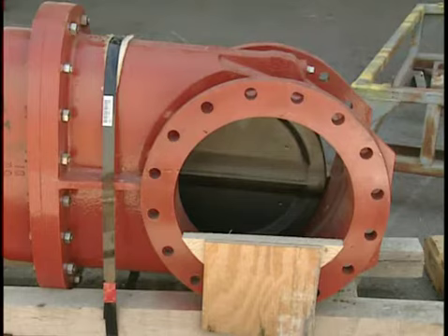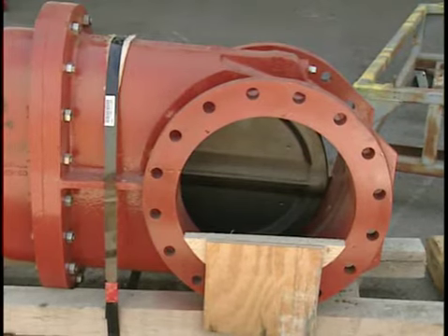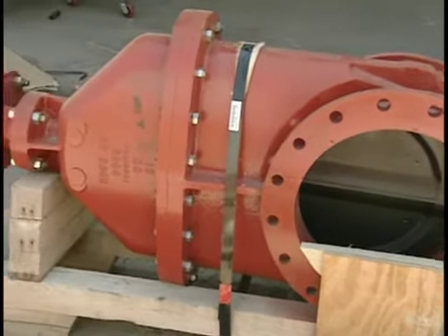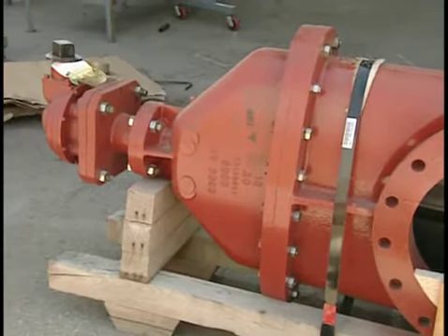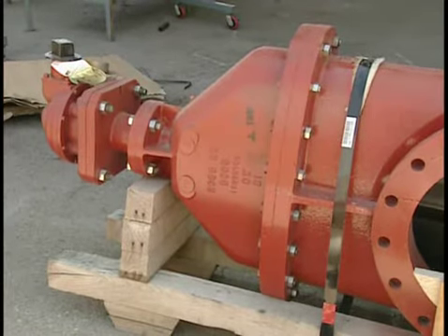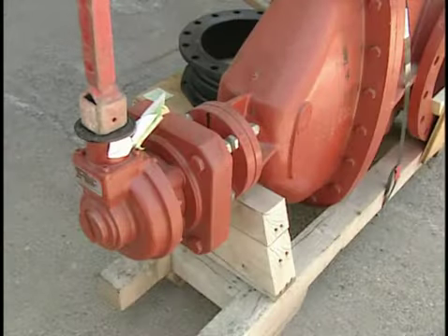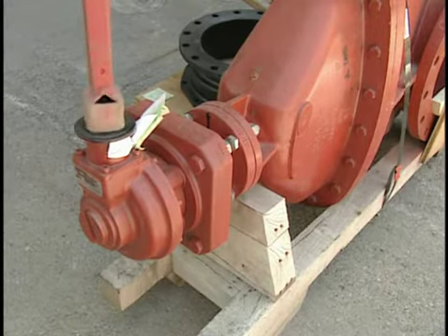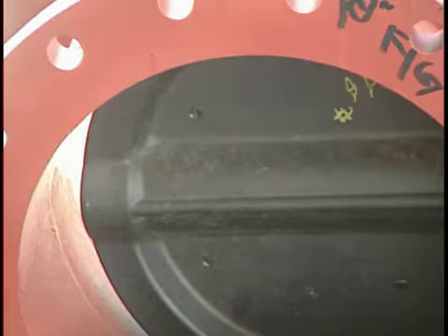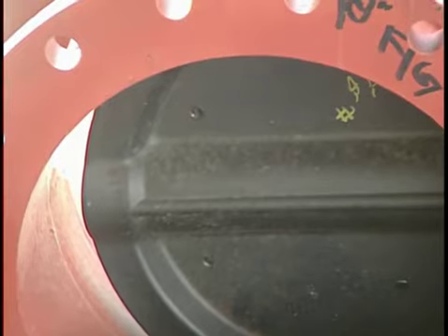Horizontal gate valves are like other gate valves, except they are designed to lie on their side, which helps in the case of large valves where it would be difficult to lift the weight of the gate. Horizontal valves are also used when a large diameter main is buried with little cover, and a vertical valve would extend above or too close to the surface.